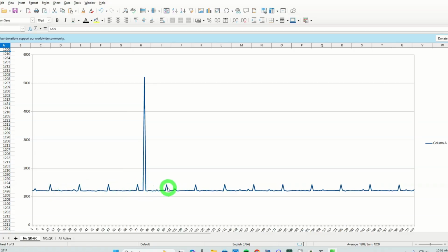That's the big spike here. And then these other ones, this is some task that I'm running intermittently. It's very minimal impact, probably 200 microseconds, somewhere in that neighborhood. But where we're at is about, we'll say, 1200 or 1.2 milliseconds for the loop running without a tiny code reader and without garbage collection.